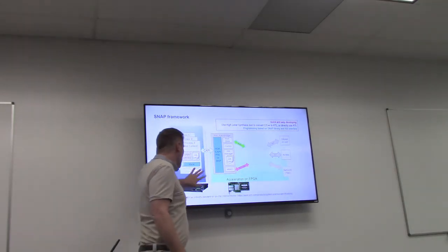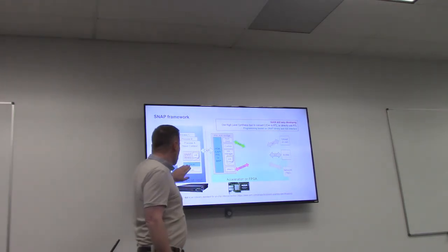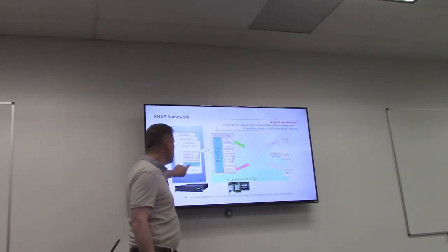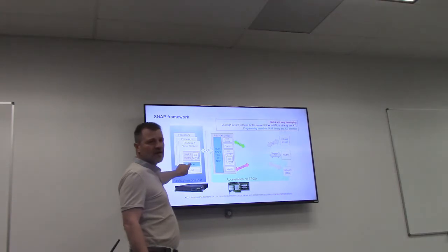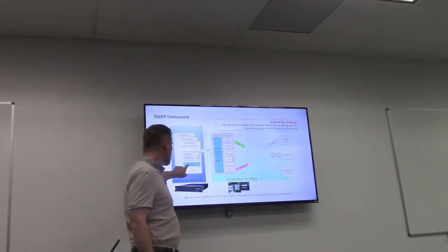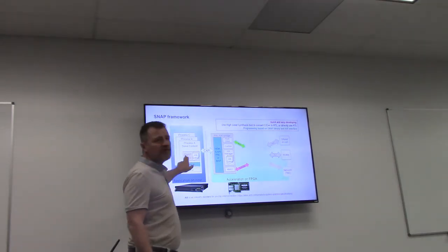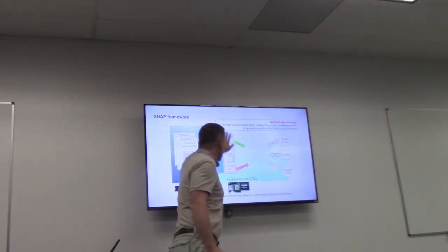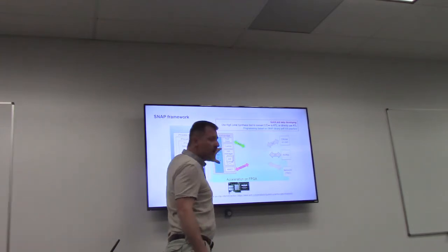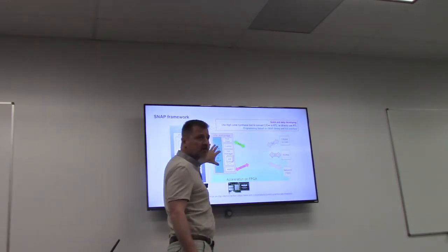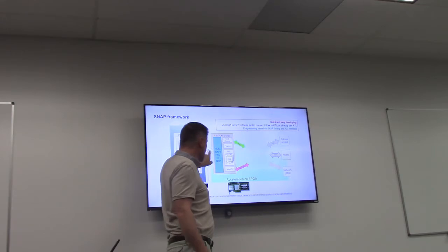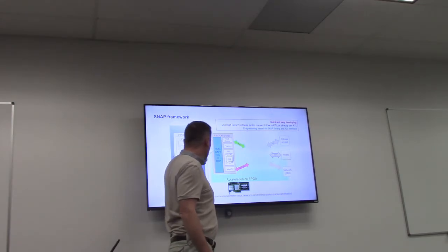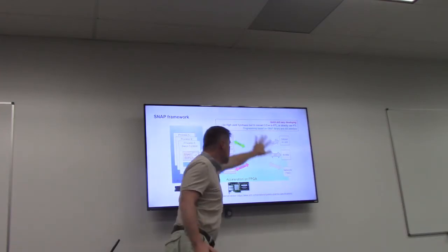So we have our power machine. We just need a very teeny, very simple libcxl library for the CAPI connection. We need a very small library for SNAP. We'll see how SNAP is taking care to offer, so that's the SNAP area. This is the hardware that IBM is providing as an encrypted file, which will make the connection between your host memory and host to the FPGA, that's the FPGA side.